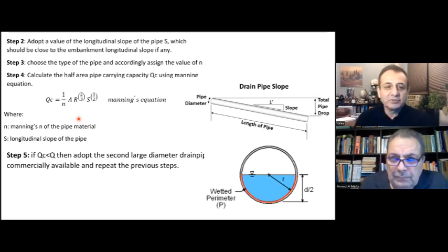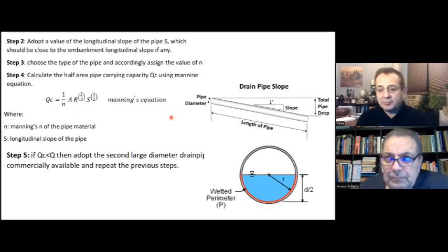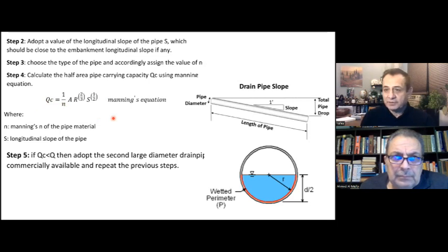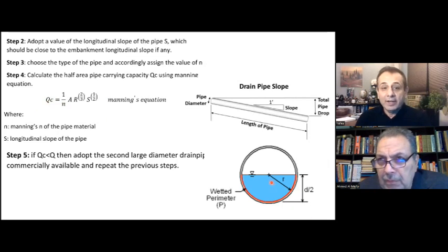So those companies usually have small labs. They produce the pipe and put it at a certain slope, and they run the flow with a flow meter so they can measure the real flow and use this equation with the measured flow to obtain the n values. They repeat it for different pipes and give you the average n value. A is the area of the flow.